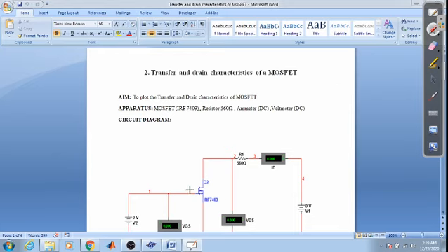there will again be three terminals, but now they are named gate, drain, and source. So these are the three names which you need to remember: gate, drain, and source. In order to turn on this MOSFET, we need to provide a sufficient amount of voltage between gate and the source. It is not current, remember, it's not current, it's the voltage.